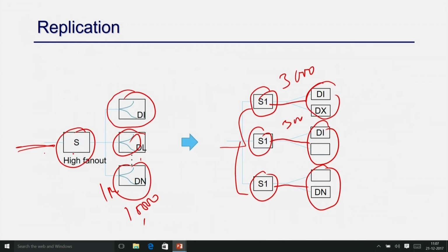So, what I just talked about, I just split this source into multiple sources now. And now I say there are 10,000 fan outs, how to club, which 3000 I should put as the output of this, which 3000 I put as the output of this, and which 3000 I should put as the output of this source, right. Here I should always maintain the hierarchy of your design.